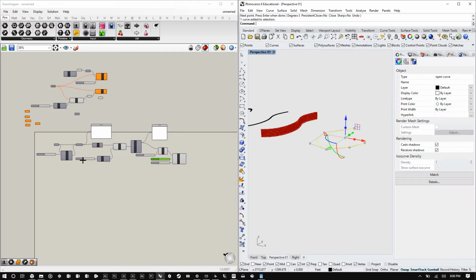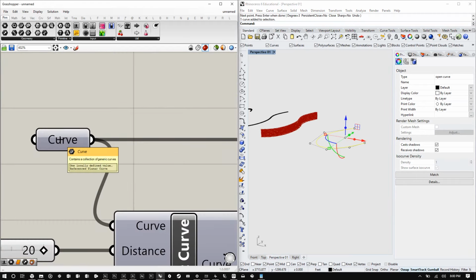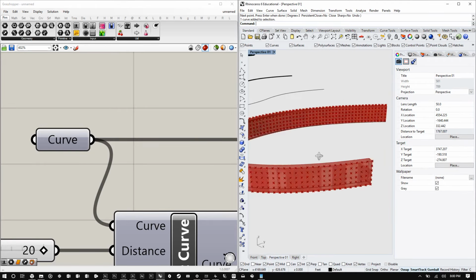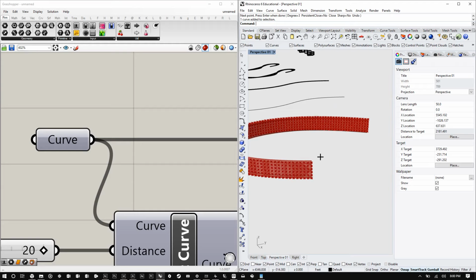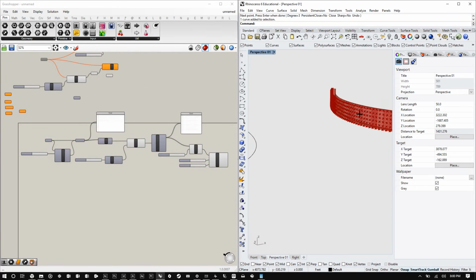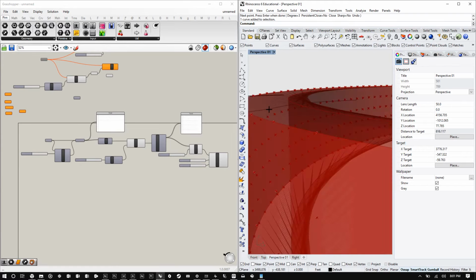So if I select this curve and I go way back to the beginning and make that my main curve, the entire process is going to be automatically done on that new curve. So let's say your design changes and you don't want to have to rebuild that wall: offset, loft, extrude, explode, select the surface, run a divide surface command, etc. You can have that, it's already been built out in your script. Make sense? Yes. Cool. Okay.